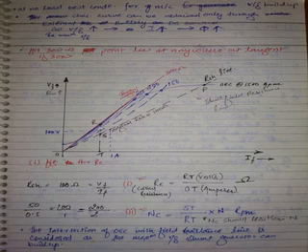Listen carefully, here there's a very important logic. If a machine has 900 RPM critical speed, and if a machine has 100 ohms shunt field resistance, let us say this is OCC at 1500. You want simply the critical resistance of this machine, not the original field resistance. What will you do simply? Plot a tangent. You have to plot a tangent.